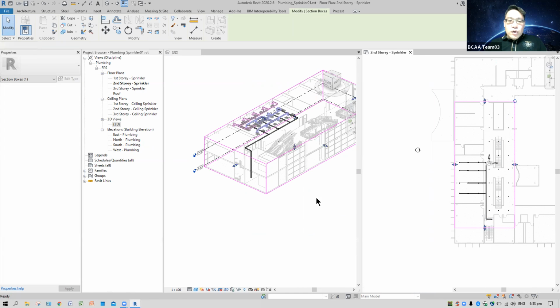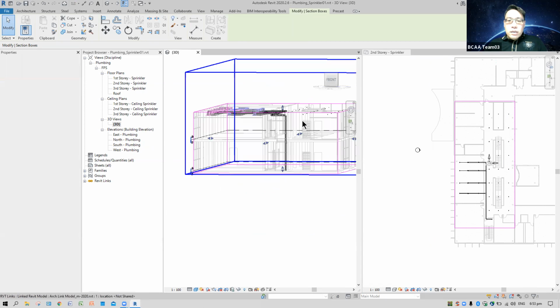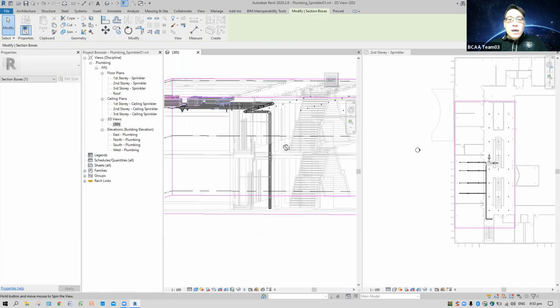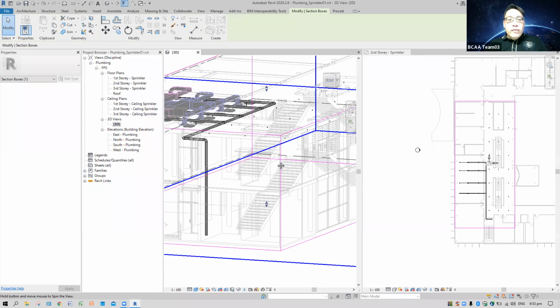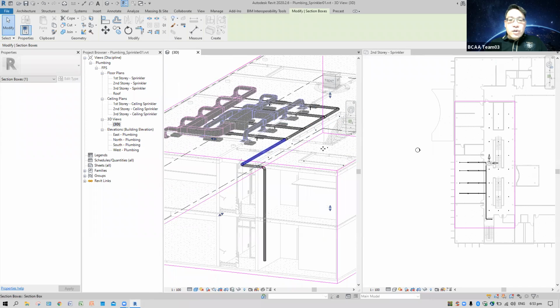As for the height, of course, must come to your 3D here. That one you must drag out a bit long, so they can see the full ceiling height and the full duct. Then from here, you notice what is the clash. Any clashes now, you can see clearly.